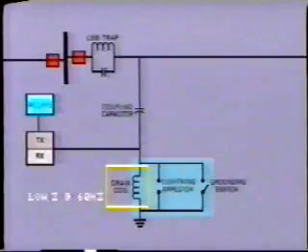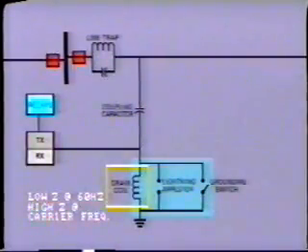As you can see, it is connected between the coupling capacitor and ground. It has an inductance designed to give low impedance at 60 hertz, but a high impedance at carrier frequencies. So the coupling capacitor is safely grounded by the drain coil. The high-frequency carrier signal is connected to the ungrounded side of the drain coil.